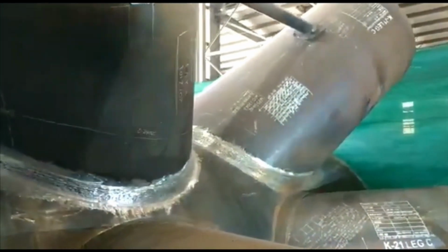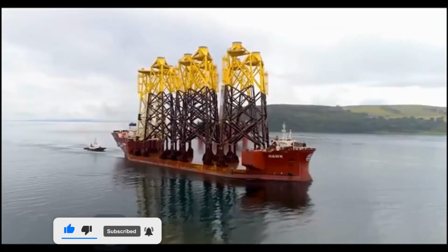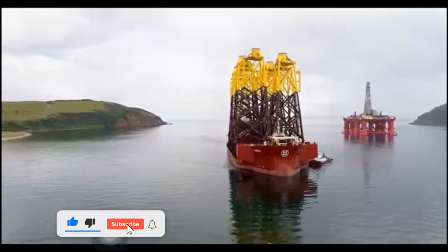Some of the most challenging structural steel welding and inspection problems are encountered during the construction of round tubular members, especially at the TKY node connections. Often these are not primary load carrying structures or they have limited structural functions. Nevertheless, in the offshore industry, tubular TKY construction is used as a primary load path for structures such as